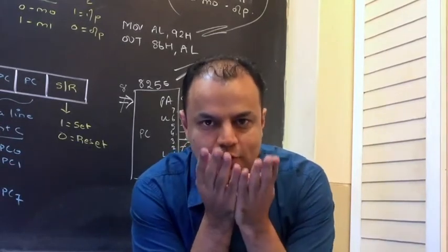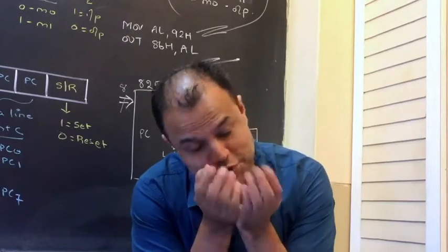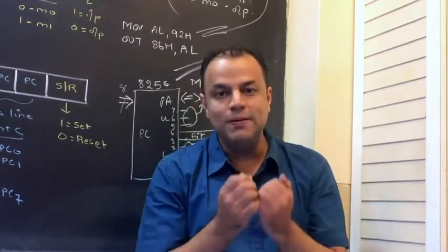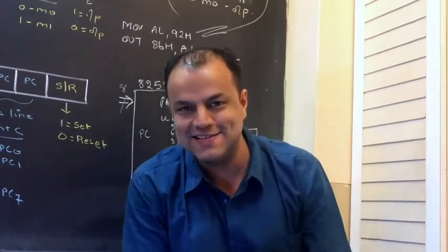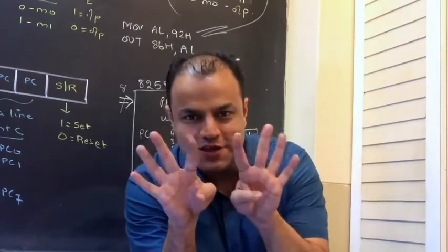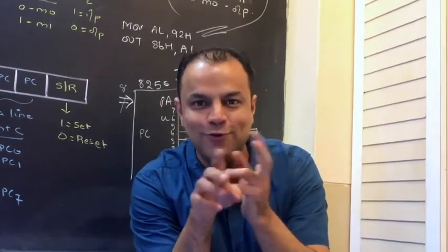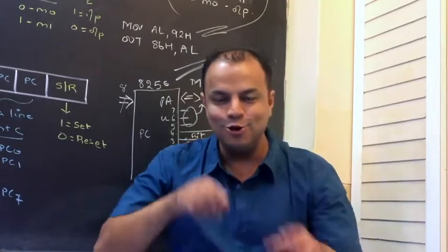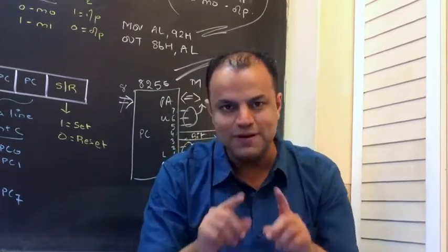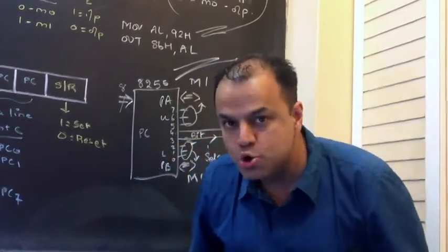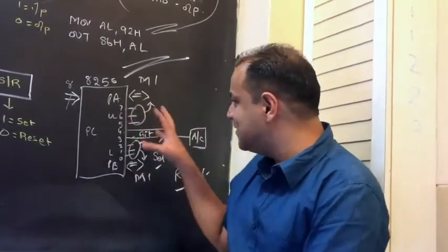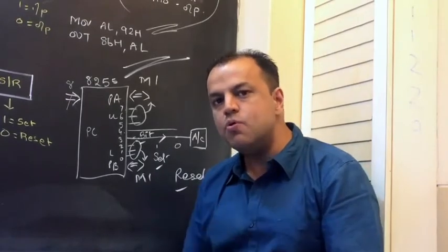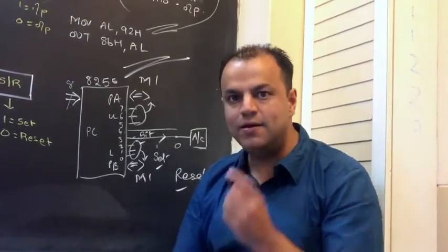port. Till now, we thought you operate on the whole port, which is true for all ports, including port C. But additionally, because of this command called BSR, you can individually make any line of port C 1 or 0 without affecting the others. That's the meaning of bit set reset. You can pinpoint on one bit and individually make it 0 or 1. So what did it suddenly do? It suddenly transformed port C from being one 8-bit port to becoming 8 independent 1-bit ports.